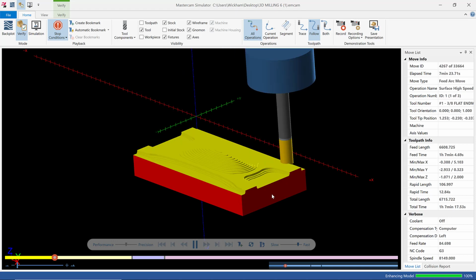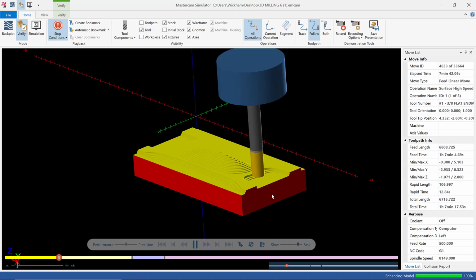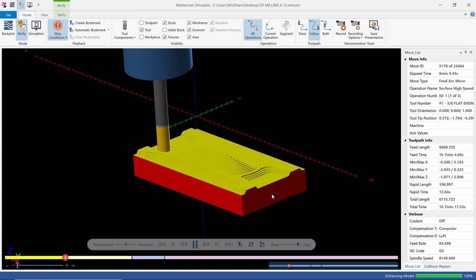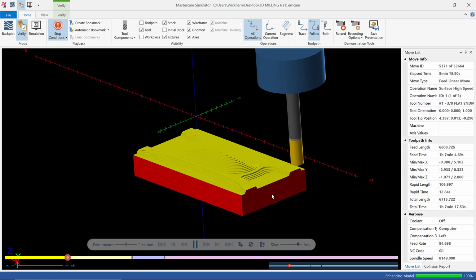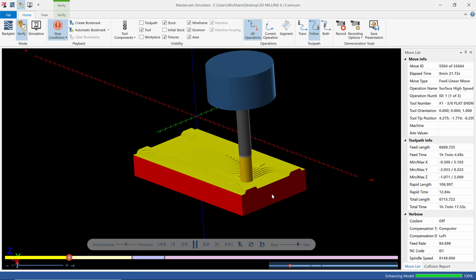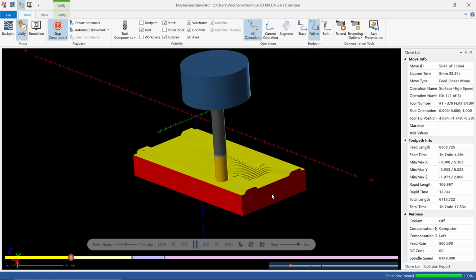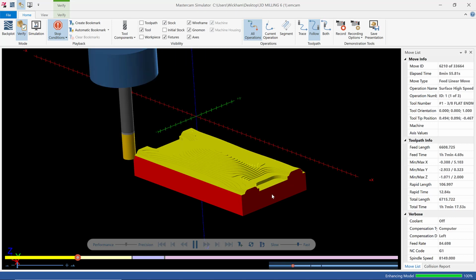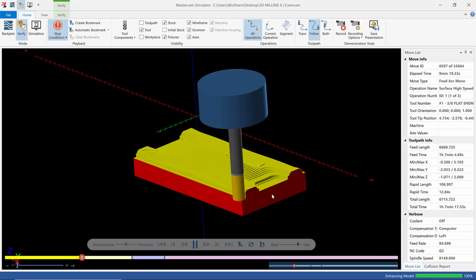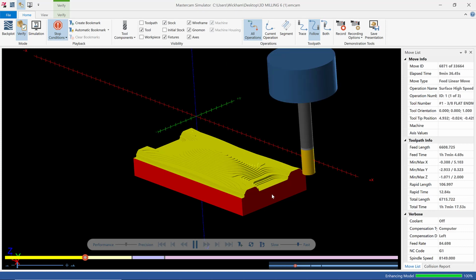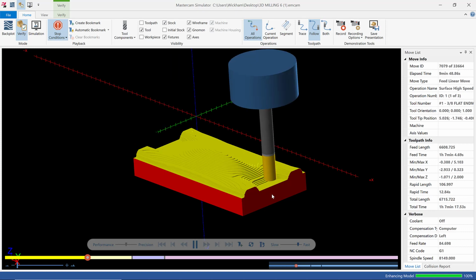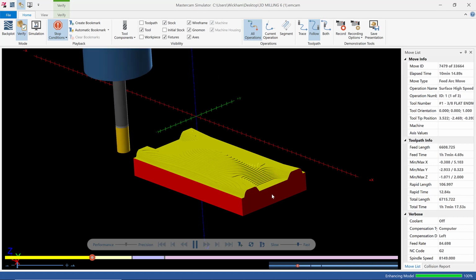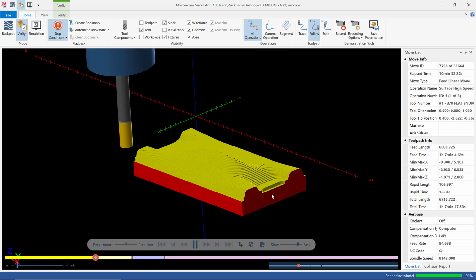So the roughing, again, like I said before, the stairs are pretty even. The upstairs, not the upstairs, but the upsteps look good. The more even it is, the faster you'll be able to run when you get to machine tool. You don't want crazy load changes on the cutter. You can see that the bar at the bottom all the time is in finishing, and that's what you want. You want to get the material out of the way and let it finish on its own, because generally when it's finishing, you're pretty safe to walk away.